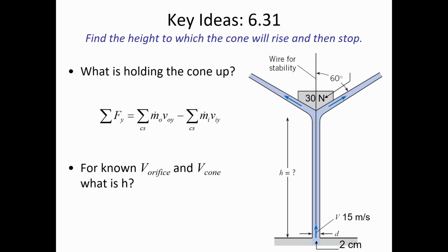Think about what it would look like if you had a cone intercepting the jet. This isn't two streams. This is actually a cone-shaped stream that we're just looking at a cross-sectional view of. So you don't have to put a 2 into the equation. It's like an outflowing jet where only a portion of the velocity is vertical, because some of it has been deflected into the horizontal.